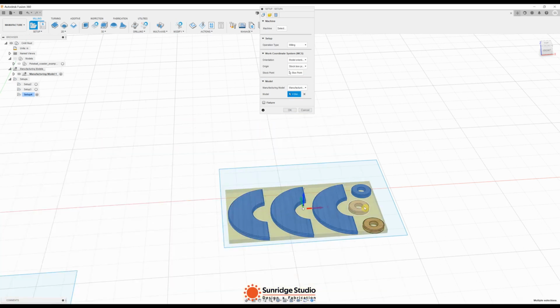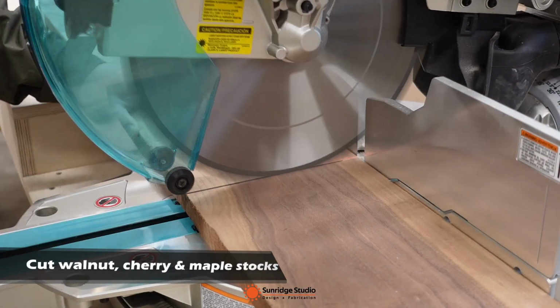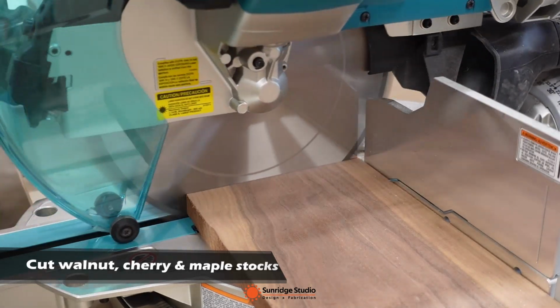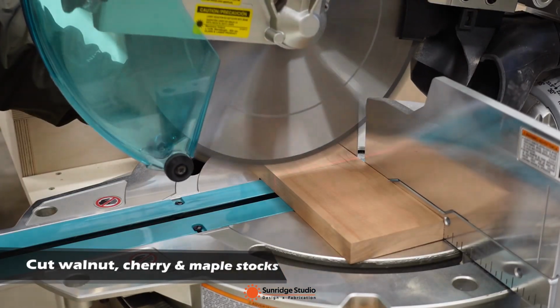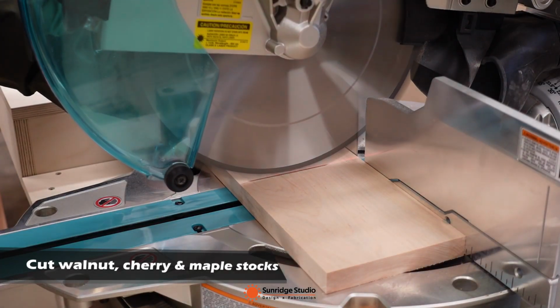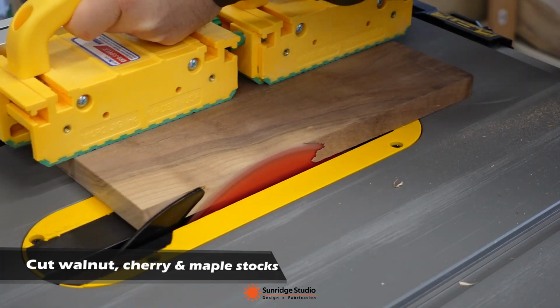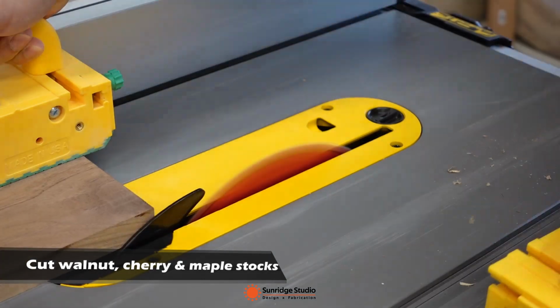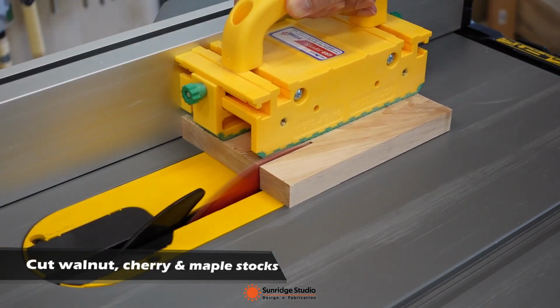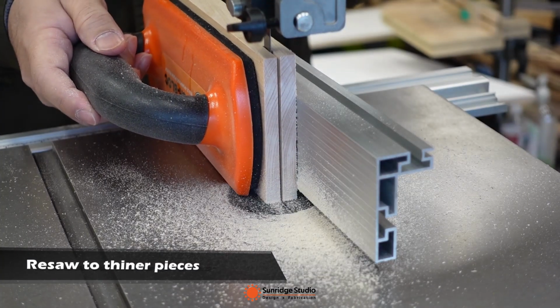Now let's start to build these coasters. First, I used a miter saw and table saw to cut walnut, cherry, and maple to the required length and width. Then I used a bandsaw to resaw the pieces, as we only need about 1/4 inch thickness for making coasters. To hold the stock, I just used blue tape with CA glue.